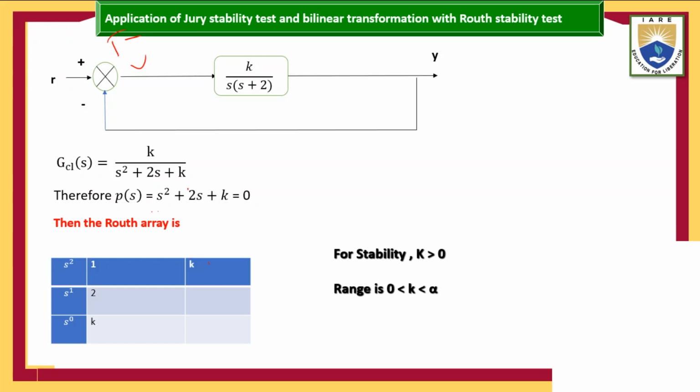After that, I am going to take the absence of the pulse function and zero order device. So the only function is K by s into (s plus 2) with unity feedback. In the case of the zero order device and the pulse function, we got the K range value.